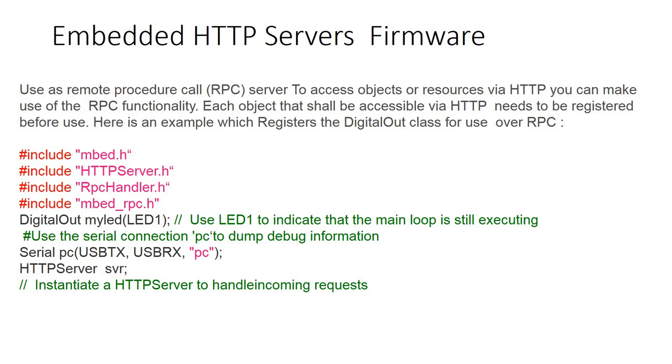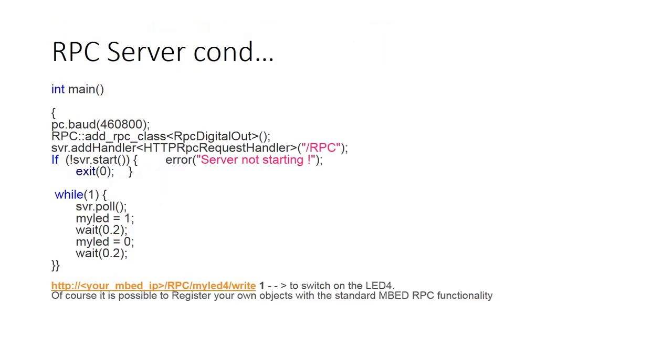You have to build the server on a chip, on a microcontroller chip. That part, how to design the hardware, will be discussed a little later, but we start with the firmware. So you have to use the MBED library. It's an online compiler. So you use certain header files and you use the HTTP server class. After that, it's a small little program. This much program is sufficient to create a simple server.